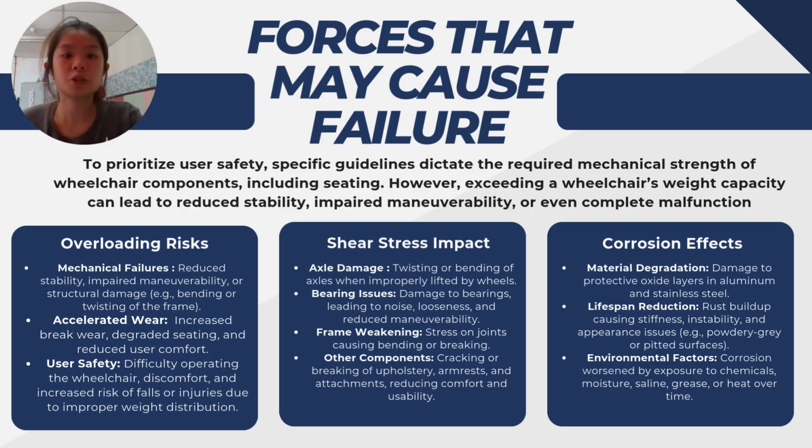In overloading risk, first we'll talk about the mechanical failure, which reduces stability, impairs maneuverability, or causes structural damage. Second, we'll talk about accelerated wear, which increases brake wear, degrades seating, and reduces user comfort. Lastly, the user safety, which is the difficulty in operating the wheelchair, discomfort, and increased risk of falls or injuries due to improper weight distribution. Next is the shear stress impact.